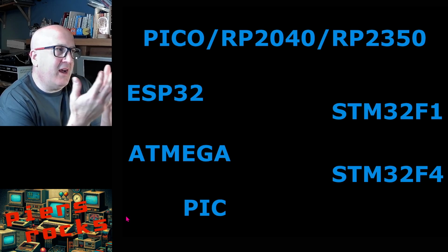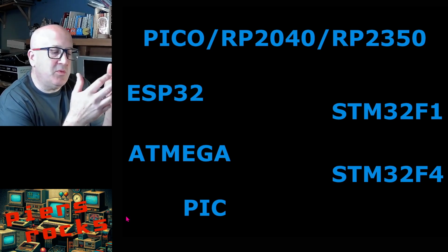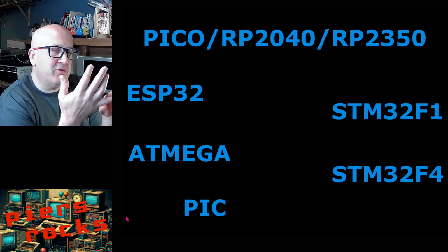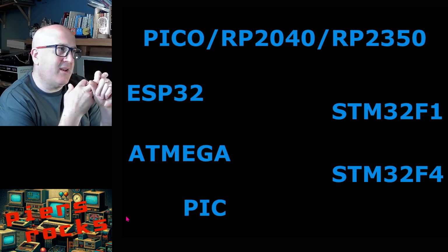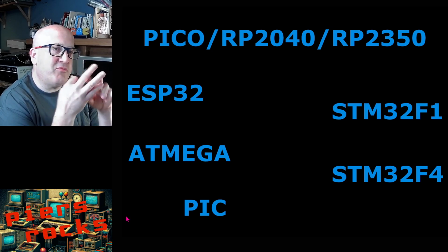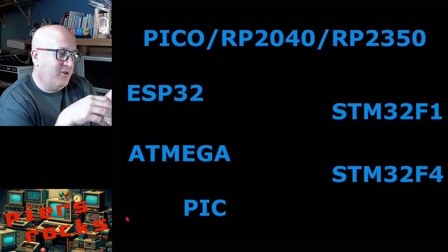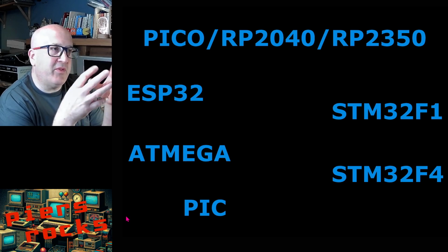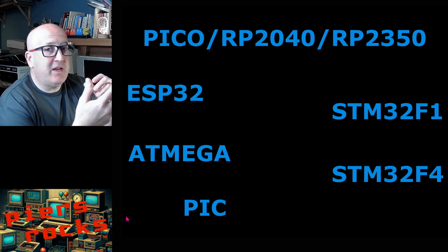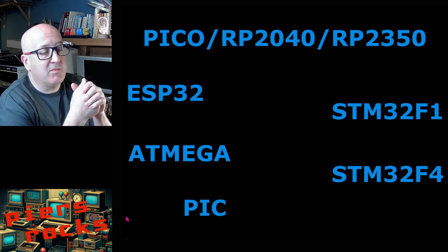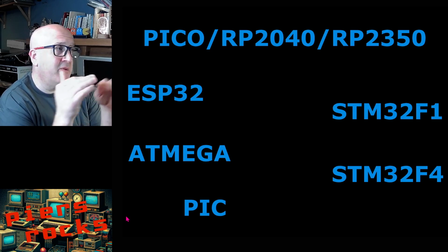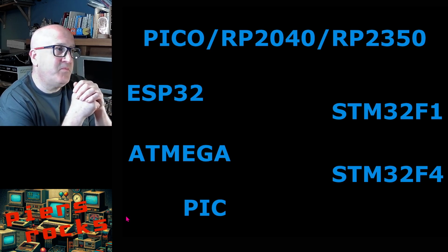But they don't have 5-volt tolerant GPIOs, and you need at least 22 pins for this application for all your address lines, your data lines, and your chip select lines. And that would have meant 3 8-port level shifters on the circuit board, and I really didn't think I could justify that. And to fit it in the same form factor, I figured I was probably going to have to go for a 4-layer PCB, which I really wanted to avoid for cost and complexity reasons. So with a heavy heart, I discounted the Pico MCU.